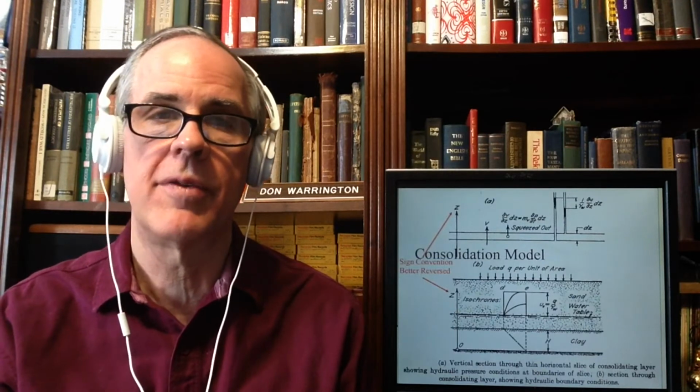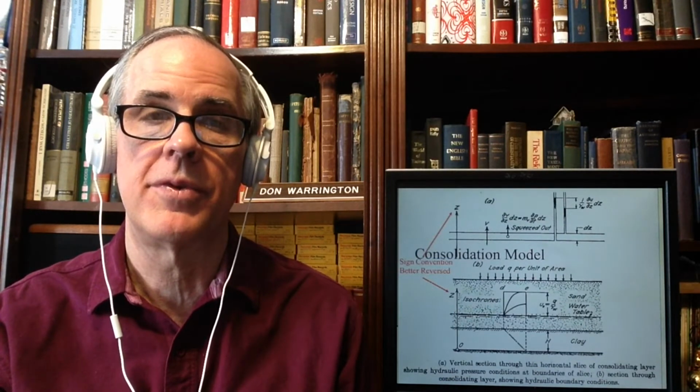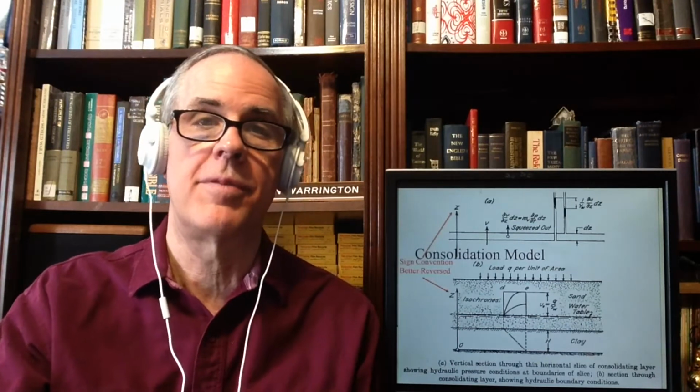It wants to leave, and it does leave by whatever path it can find. And we're going to talk about how important it is to know what that path is. Once the water leaves, the void ratio decreases and the soil settles. But that's not an instantaneous process, because the clay particles, being small and compact, don't want to give up the water without a fight. And that fight can take months and years.